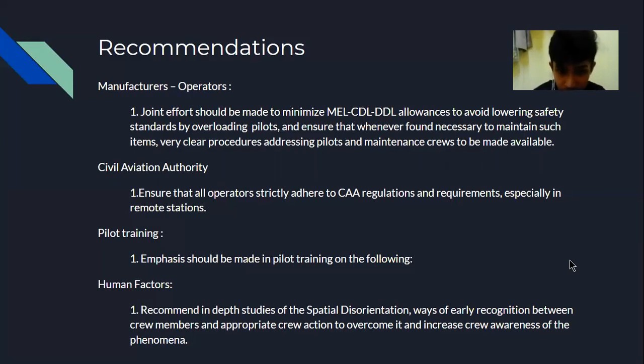A joint effort should be made to minimize MEL, TDL, DDL allowance to avoid lowering safety standards by overloading pilots and ensure that whenever it is found necessary to maintain such items, very clear procedures addressing pilots and maintenance crew are made available. Clear engagement status indication for the autopilot should be made available to the crew to avoid any possibility of incorrect perception or ambiguity.